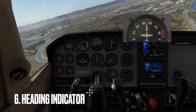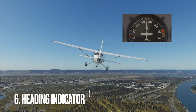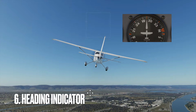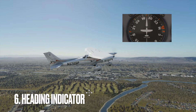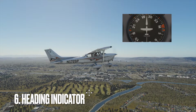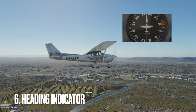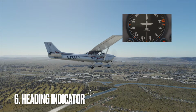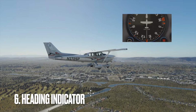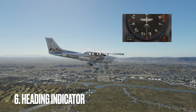The heading indicator displays the aircraft's heading in degrees. Pilots rely on the heading indicator to maintain the desired direction of flight, especially during navigation and course corrections. For example, during a cross-country flight, the heading indicator helps the pilot maintain the intended course by providing continuous heading reference. Accurate heading information is crucial for navigation, especially when flying to specific waypoints or destinations.